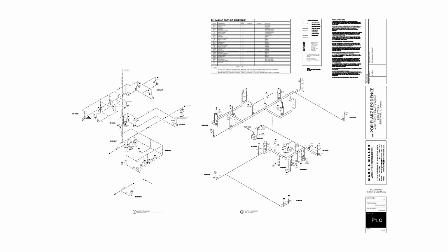And then we'll have, required by the municipality, usually a plumbing diagram showing the layout of the supply pipes on your right and the waste and vent lines on your left, with a plumbing fixture schedule for each plumbing item in the project.